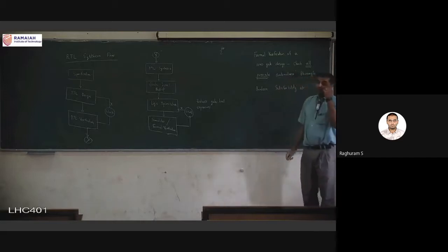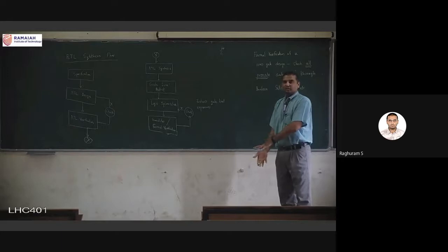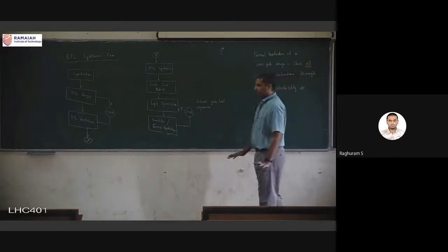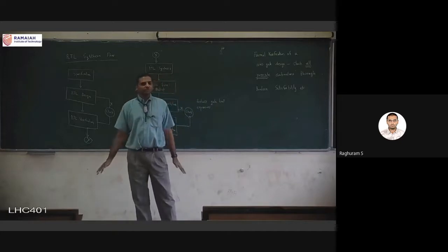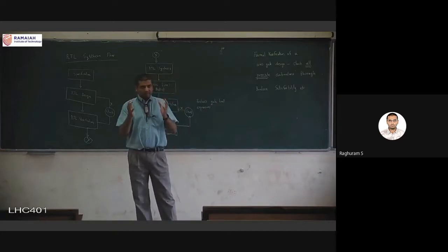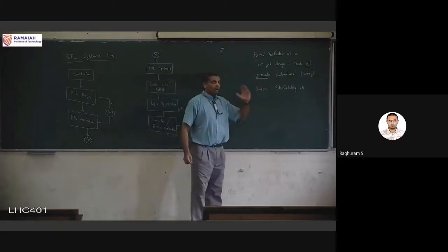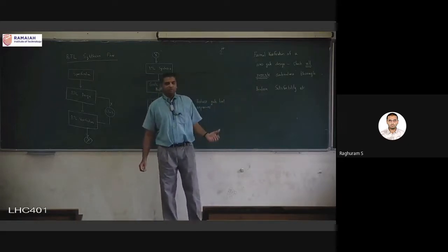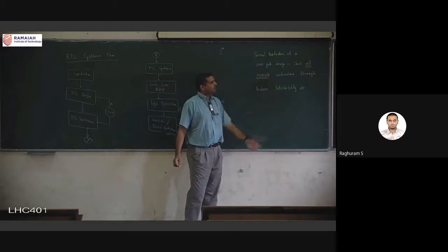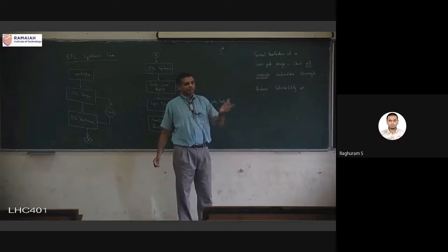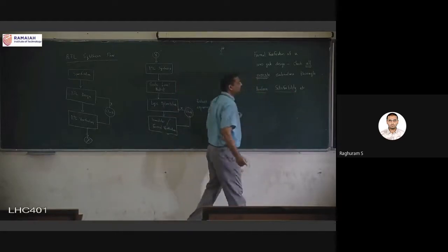formal verification doesn't mean that we do the same thing but we do simulation inside. There is no question of simulation, there are no inputs at all. Formal verification doesn't care about the inputs to the circuit, it only takes the design, and then it checks for all possible combinations. This is the whole idea. It checks for all possible combinations through different methods. One example is Boolean satisfiability.